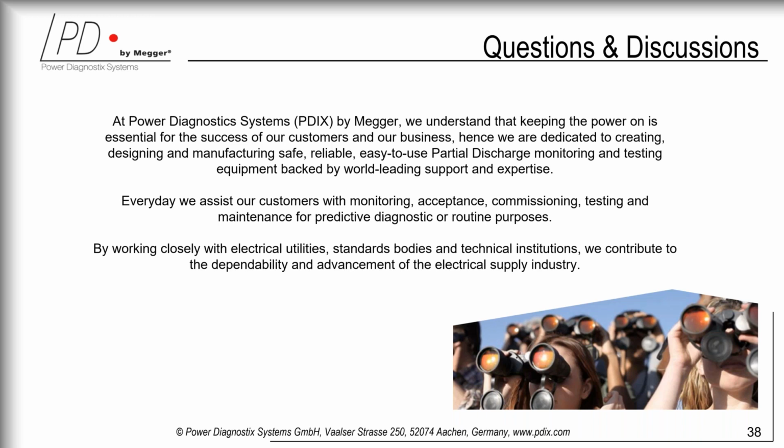Yes, for sure. So we have two outputs. From the bushing couplers, it goes into an adapter with one Teflon lead. And from there, we have two BNC connectors, and one is used for PD measurements, and the other one exactly for tan delta capacitance. And we have some customers who combined our PD measurement with a tan delta device from a different brand.